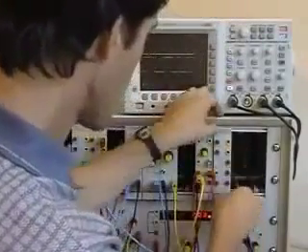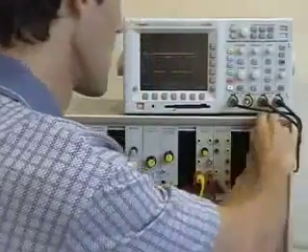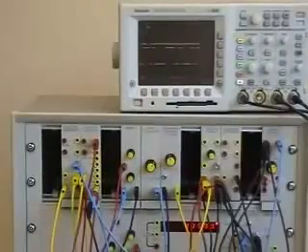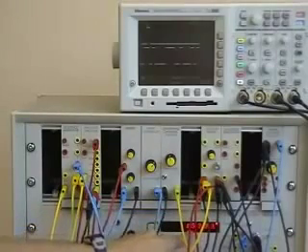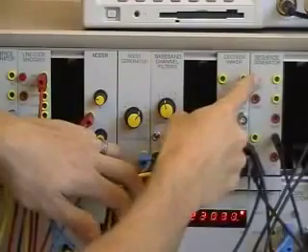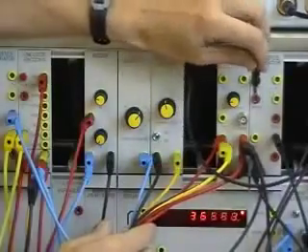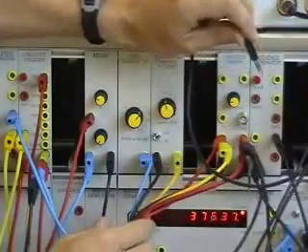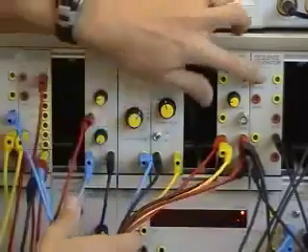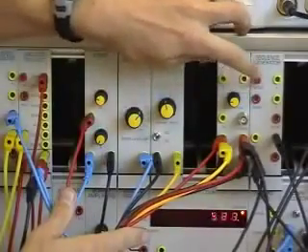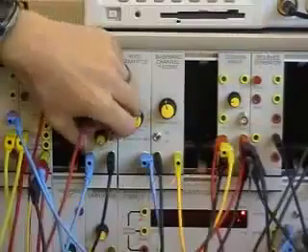Insert a local reference sequence module and error counter module to enable a comparison of the recovered data and local reference sequence data. Patch them to the pulse counter, which will display many errors being detected prior to synchronization of the sequences, as expected. A sliding window correlator method is implemented. The errors stop as the sequences are aligned. The pulse count is cleared. Sequences are misaligned again and then resynchronized using the alignment signal, like so.